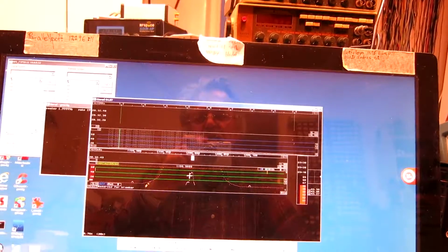And here is the signal, and I click on the signal to move it to the center, and I make averaging 1 and 1, because the transforms now span a long time. And now the frequency readout is correct.